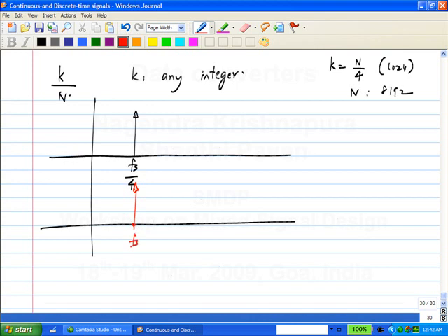You will get distortion. So where will be the second harmonic? Fs by 2. Where will be the third harmonic? 3 Fs by 4, and so on. Now for data analysis, this is sampled. What will happen because of that? This is the amplifier output, sampled at Fs. So what will you see in the DFT?